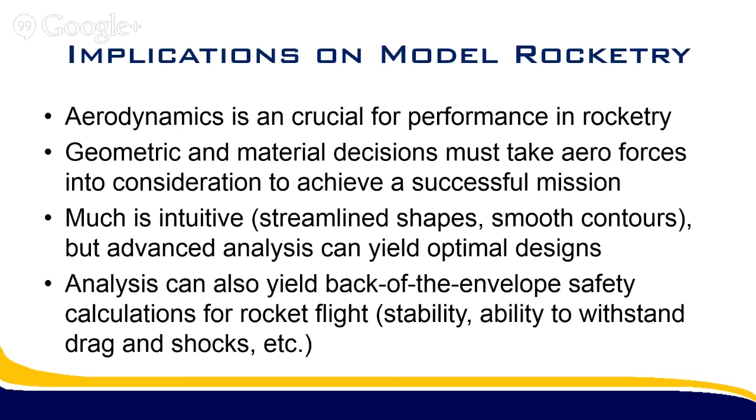So depending on the mission you choose to pursue, to make it sound very official, the aerodynamics are an important consideration to make. They definitely drive the decisions you make about your rocket geometry and the materials you decide to use, because you have to take into account those aerodynamic forces and make sure that you're able to achieve what you want to. If you're trying to go past the speed of sound, having balsa fins and a paper rocket is probably not going to do you much good.